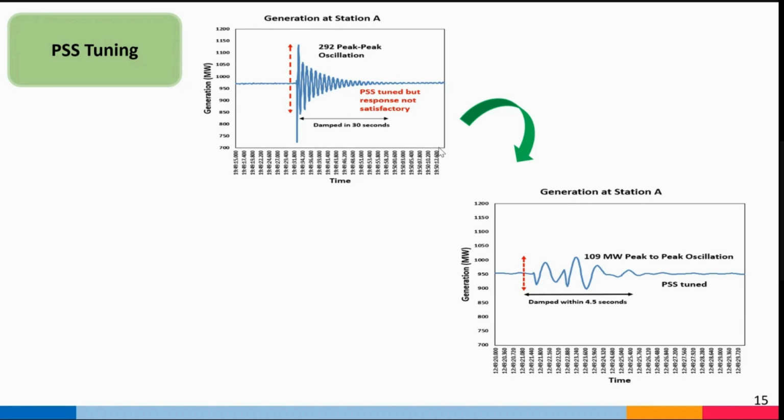So I informed you that these are basically lying in the range of 0.01 hertz, that is from the governor side. Lower the frequency, slower will be the response. So that is the governor response, 0.01 hertz.